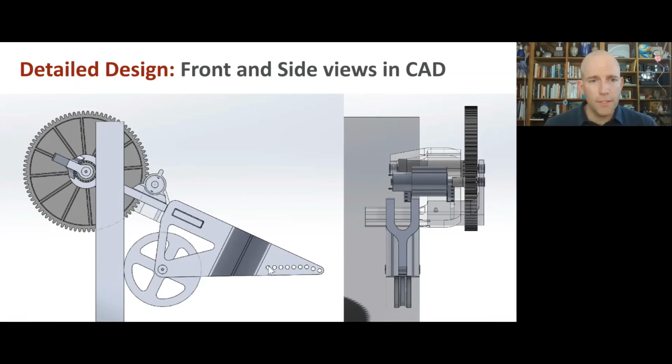And you can see here we have several different holes, and that was based on the idea that the center hole is the one that I expected to use for the loading rope. That's along these lines of action of the expected forces. But I thought, oh, maybe my coefficient of friction estimate will be slightly off. It'd be nice to have some adjustability. So I put those holes in. As we'll see, it wasn't quite enough.